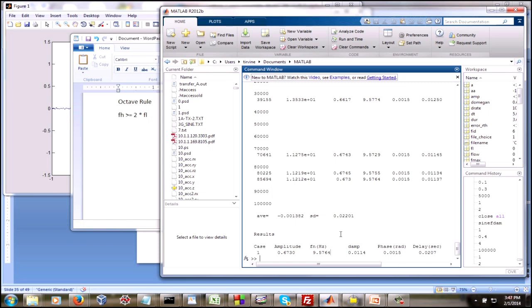Well, as it turns out, only one of those 2 options is the right one, because we don't want a 5 Hertz payload. When I say a 5 Hertz payload, in other words, if we take the payload by itself and turn it into a cantilever beam, its cantilever bending motion should not be 5 Hertz or less, even though that would satisfy the octave rule. And the reason is, with that low of frequency, that could cause some interference with the control algorithm for the whole vehicle.